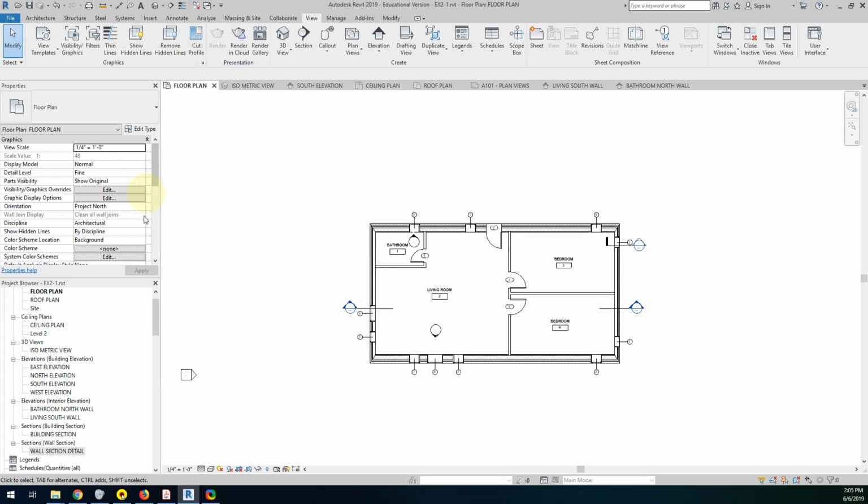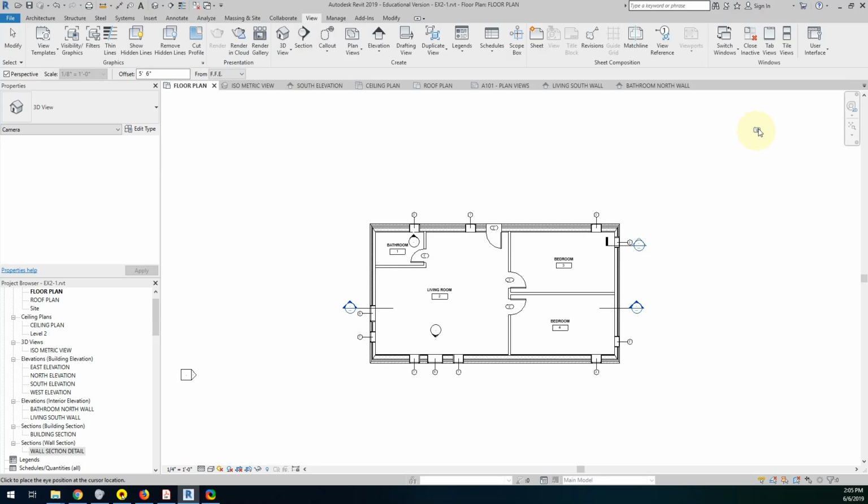So we go to, starting on our floor plan view, the easiest. Go to View, do the drop down underneath the little house, and select Camera. This is like a real camera, so we're replacing where the camera would stand first. So I'm going to start somewhere on the outside of our building, kind of far away. And click and place the camera, and then drag the target to the opposite side of the building. This is important. If I stop short, it would only render up to about this point, and only the front corner of the building. So it's going to go to the far side.